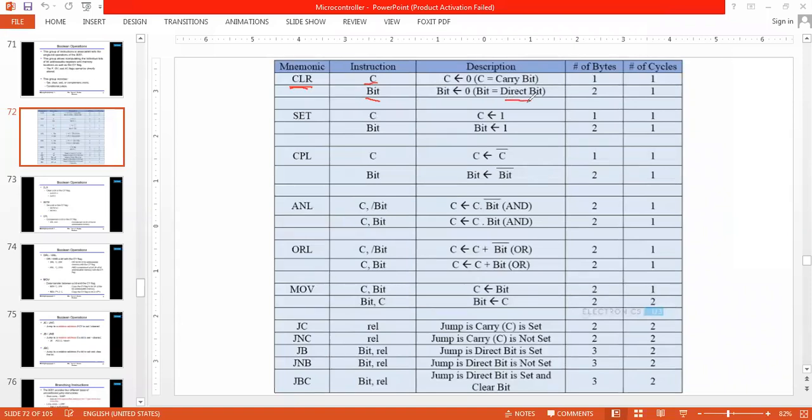Say like even if I take the P0 register, P0 register is a port 0 register. So if port 0.0, I can write port 0.0 here. CLR port 0.0, which will make the port 0.0 pin on the hardware be made 0.